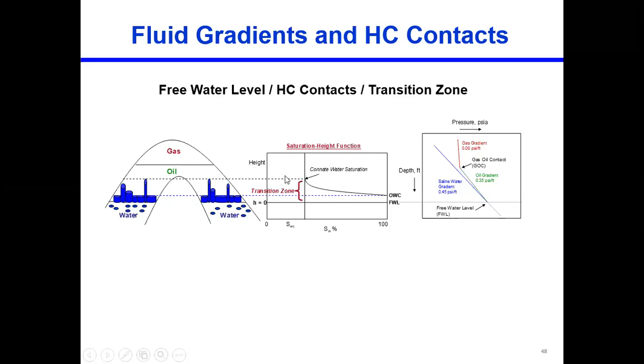Now look at this one. They are connecting this gas, oil, and this one. So between oil and water, there is some transition. So it's showing the transition stage also. So based on this pressure profile, we obtain our oil water contact, gas water contact, and exactly the depth of the gas, oil, and water.